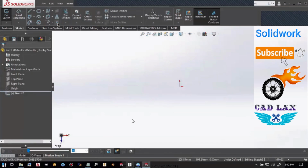Next tool is point, and point is very much useful when you are creating pattern, circular pattern. But I will tell you a few minutes later how it is used. You can see whenever I want to create a point, you have to just click on this icon and click OK. And points also have to be defined. So you can see under define, what you have to define is the location. Location to the origin. Whenever you specify the location to this point, it will be automatically defined.